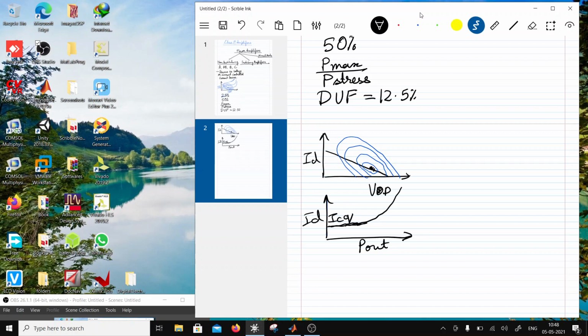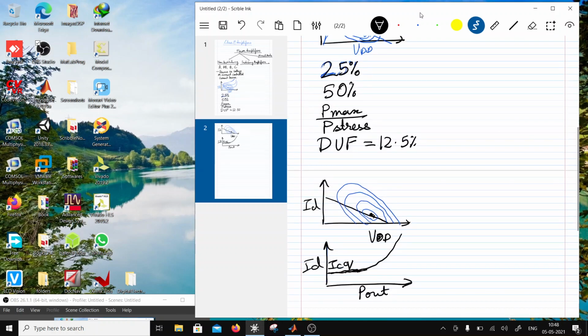So initially what happens is, if you keep on increasing the power, the current drawn from the drain increases above ICQ, right? If it keeps increasing and there is no restriction, you can deliver more and more power at a higher and higher efficiency. The clipping is going to increase, and you are going to have more DC current, right? But then there is a limitation on supply for this current, or there is a limitation posed by the channel width for a device, right? And when that happens, the device compresses, right?